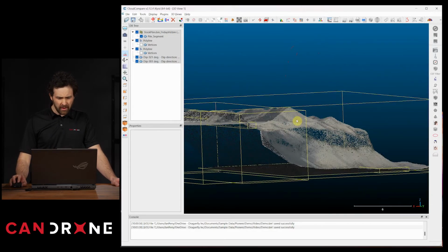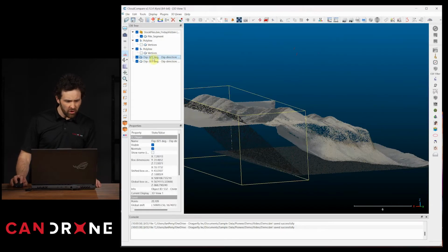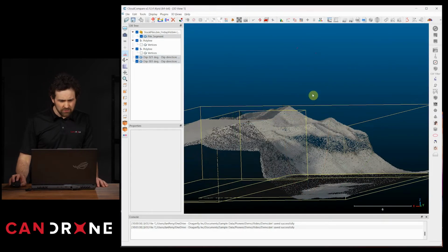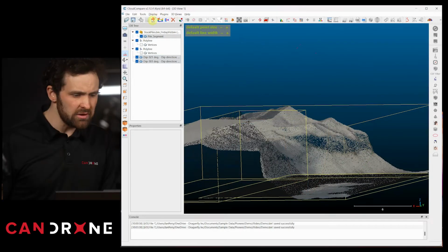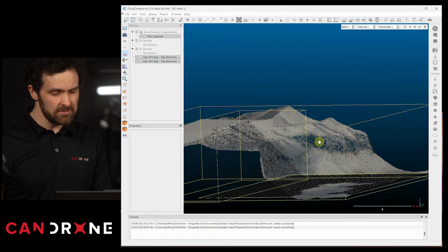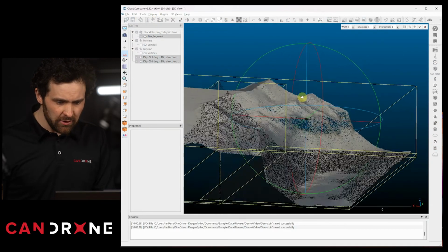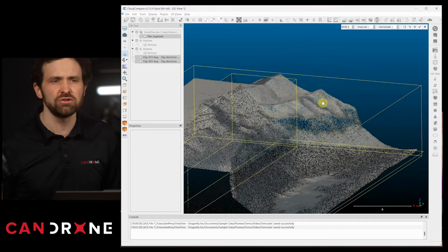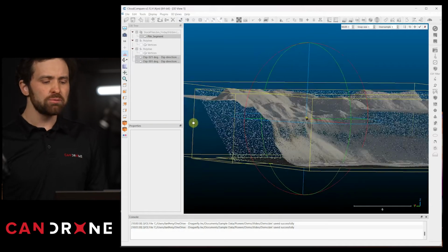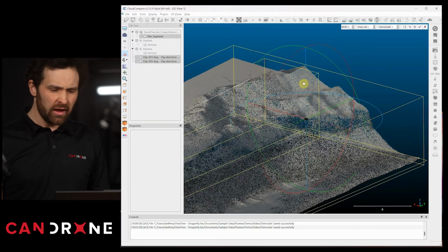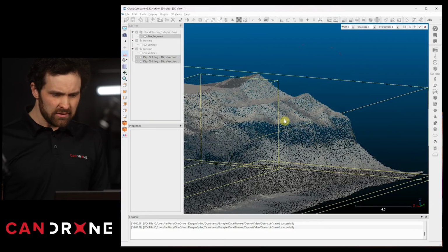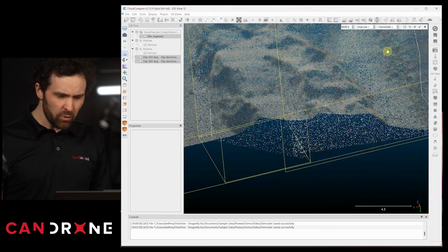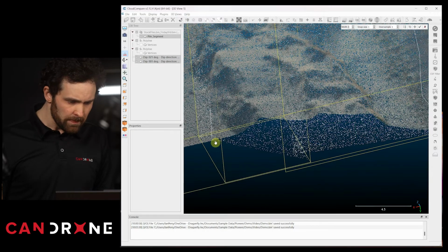To start doing that, I'm going to highlight all three clouds of interest, and I'm going to go up to the tool Trace Polyline by Point Picking once again. Now the tricky thing when you're picking points in a point cloud is ensuring that you actually pick the right points. So you have to pause and really pivot a fair bit. And I'm going to start, make it easy on myself, I'm going to start here.